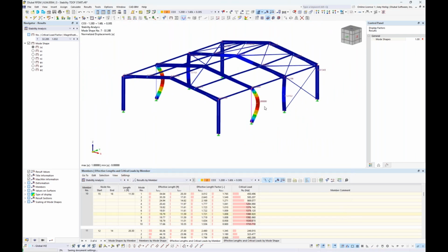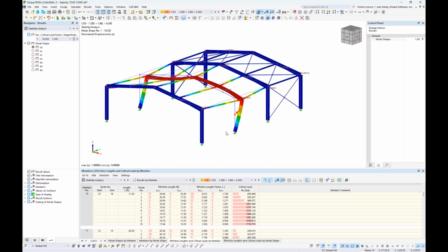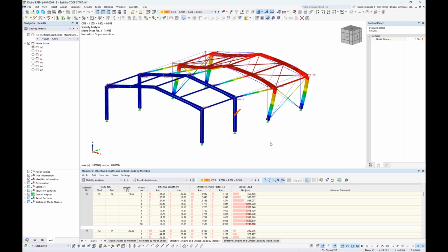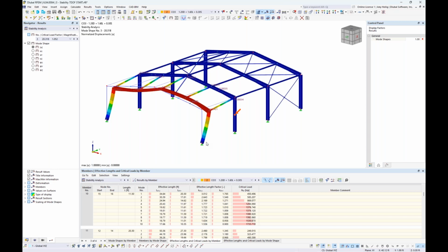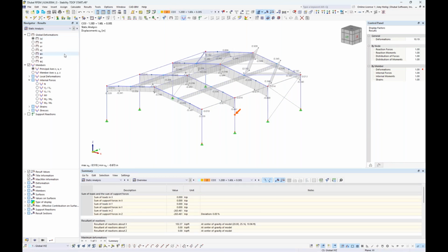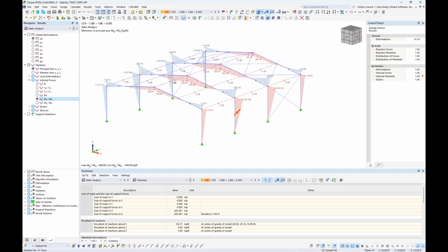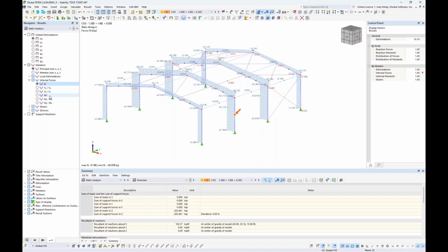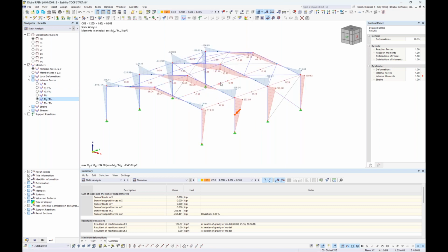Okay, so now that we have covered the basic stability mode shapes here, keep in mind that everything that we have seen so far has been based on 6 degrees of freedom. And with 6 degrees of freedom in these various mode shapes, we're really only able to consider flexural buckling. We certainly can see this with the mode shapes directly, with flexural buckling failure of the columns themselves. But if we back up a step to look at the static analysis results, or the internal forces from load combination number 3, what we'll actually see here is that we have pretty high bending forces along the length of our members. And when we look at our columns, we have pretty high axial forces, of course. When we're talking about these bending forces, for example for these beams, this should immediately flag us that possibly lateral torsional buckling is an additional stability failure state that we need to consider.